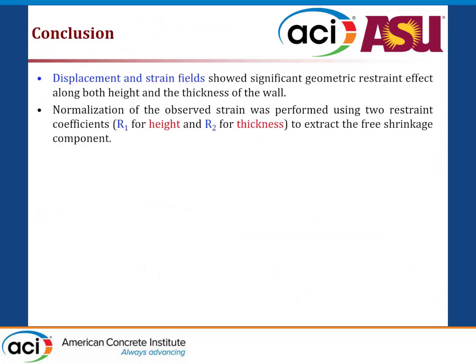So in terms of strain field displacement, we saw that we can use DIC to capture the displacement field in fresh printed concrete. These were printed concretes, and the measurements were taken from 15 minutes after printing up to 24 hours, 48 hours after printing. These are the plastic shrinkages that are usually the most detrimental in printing. So we can capture that with DIC imaging. We can understand why the strengths are different with different layer heights, print heights and print thicknesses.